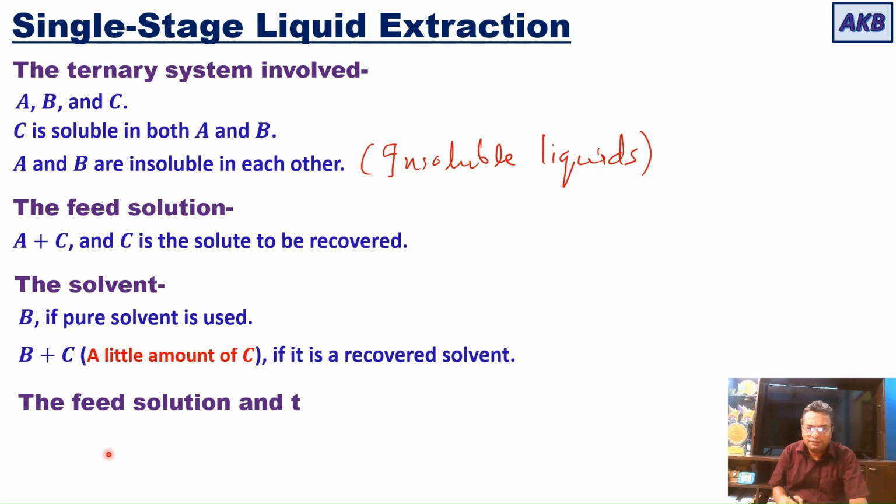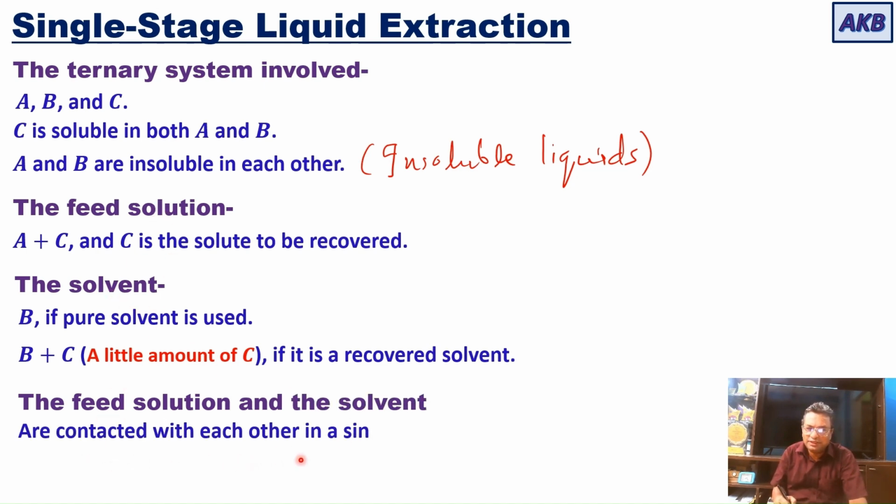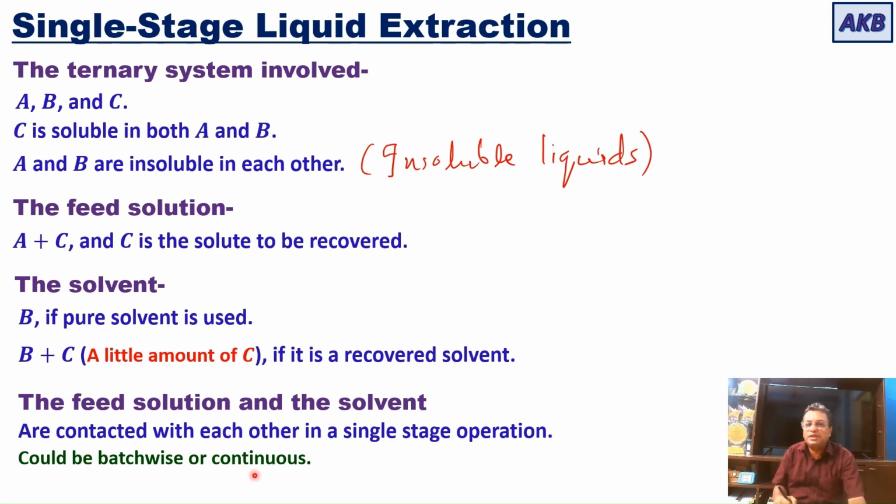Then the feed solution and the solvent are contacted with each other in a single stage operation. We are discussing this operation where the two insoluble liquid phases are contacted in a single stage. So this operation you can carry out in a batch-wise manner, or you can carry out in a continuous manner. So the single stage liquid extraction that we are talking about could be a batch-wise operation, or it could be a continuous operation.